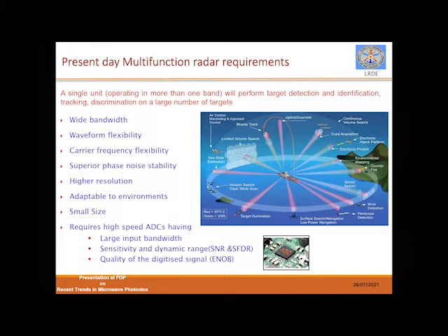They are not tapping, it is called electronic countermeasure. They will understand that, and they will try to pump more and more energy towards us in the same frequency, so our receiver will get saturated. So we don't play a single frequency during the transmission. Randomly, without having any order, we will be playing different frequencies.